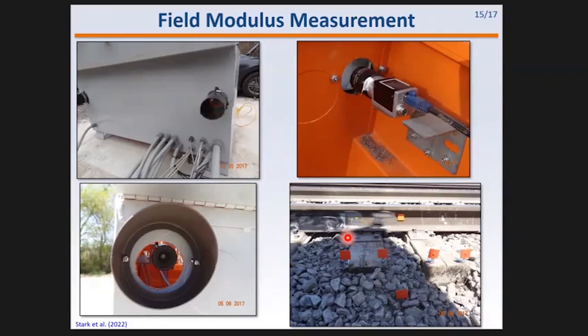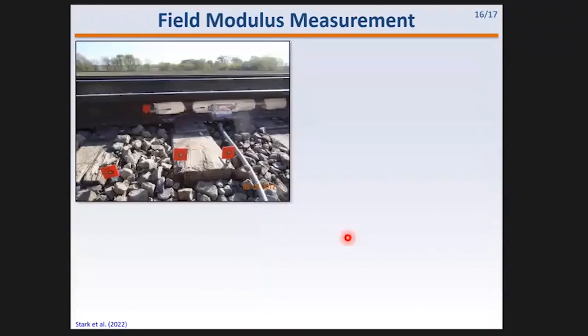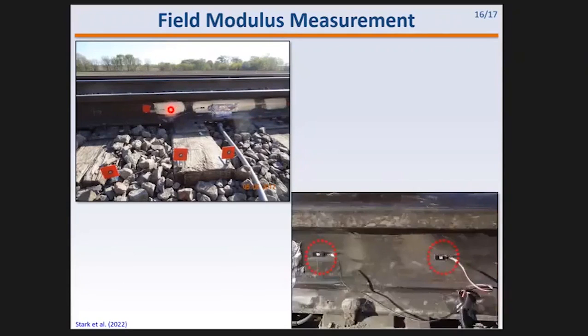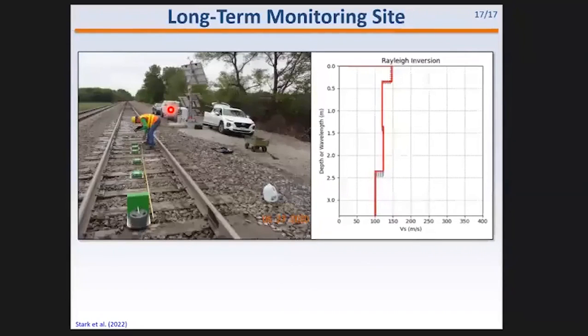Also, with the instrumentation site are some rail strain gauges, as you see here. They're placed on the rail, one circuit inside the crib and another circuit over a tie. And so that now enables us to estimate the amount of load going into the tie by subtracting the crib and the distributed load, which comes off this circuit. Here's a close-up of the strain gauges on the rail. So now we've got wheel load over the tie, and we have the transient displacement of the tie, which I'm going to use to calculate modulus.